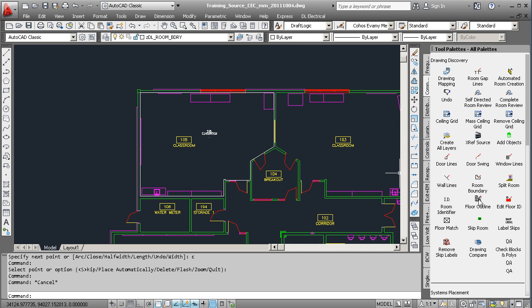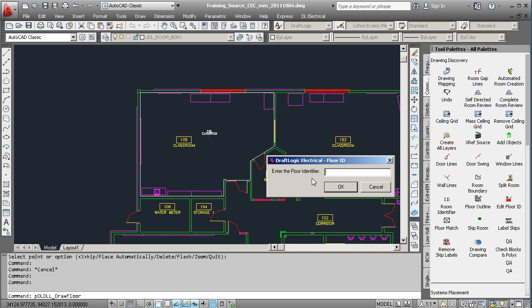Similarly, for the floor, we would go through all of the rooms, all of the spaces, and do that. Usually you're going to follow a room boundary, but if you have a space where you want part treatment in one area and part treatment in another, you would use more than one room boundary inside that room and cut it into multiple spaces. This might happen, for example, in a corridor where there's corners and stuff, and you want to treat the sections of the corridor as more rectangular spaces for better generic lighting placement. Or, for example, a large room which has half T-bar and half open ceiling, and you're going to want a separate lighting treatment for each area.